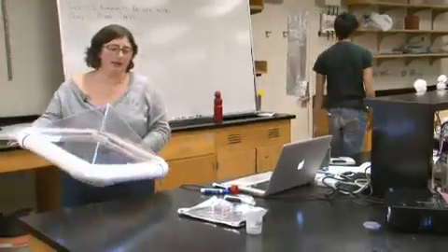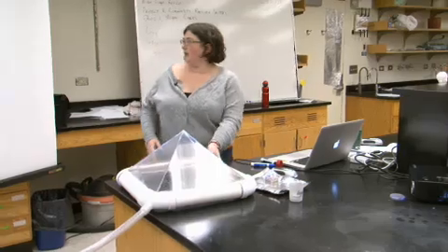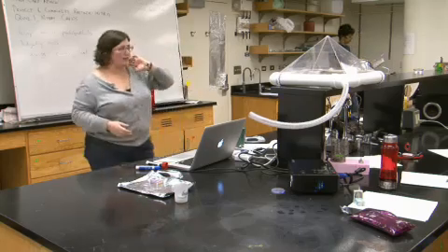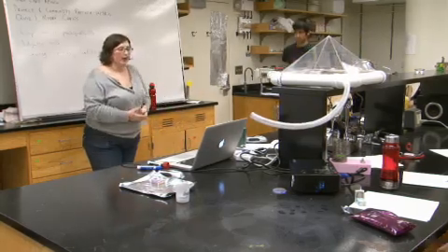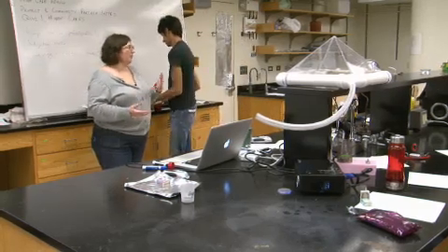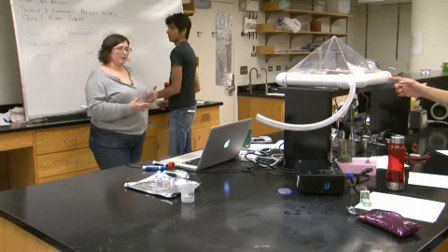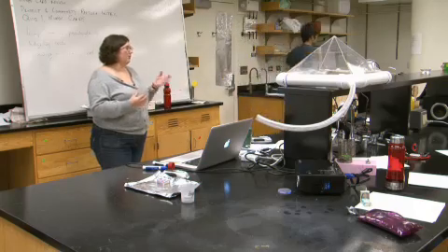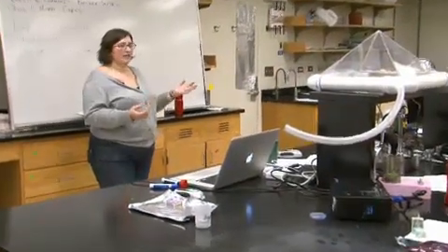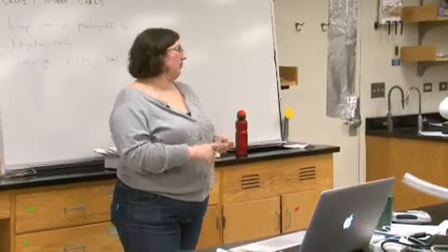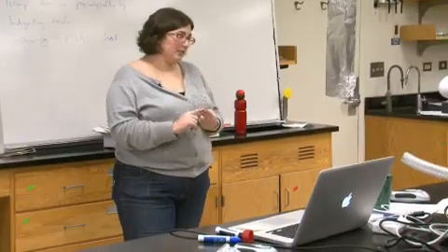batteries, these deep cycle batteries that need to be recharged regularly. And the batteries need to be refilled with distilled water. And if you don't use distilled water, you shorten the life of the batteries by a really significant amount. And these are very expensive batteries that make up a big percentage of the system. And people are living in islands and coastal areas where the only way to buy distilled water is to travel by boat for a few hours, which is expensive, and when there's any sort of weather is impossible. And so people will naturally just use regular water rather than distilled water.